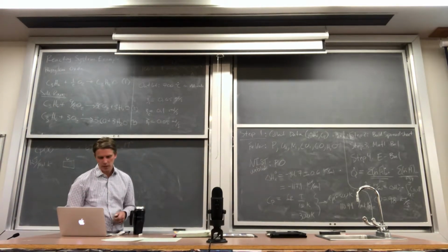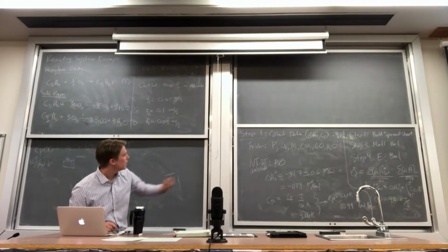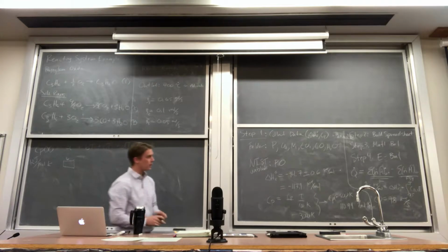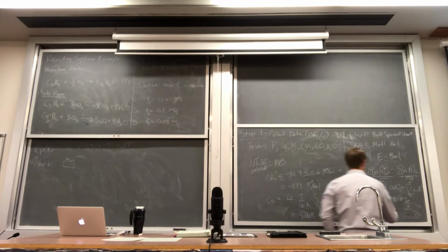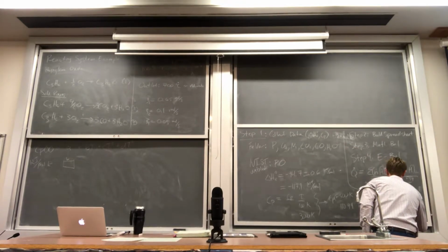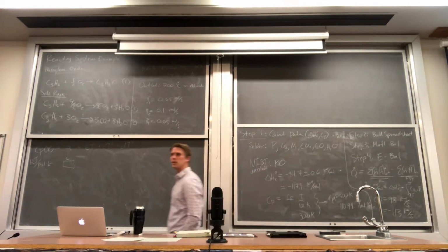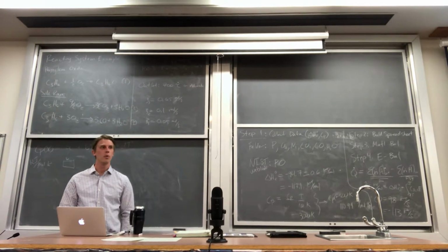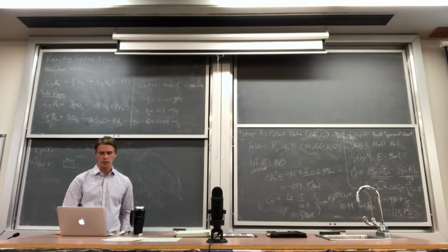Now let's say, for example, I don't trust my propylene oxide heat of formation. Let's change it to the minus 117. How did that change our result? It's significant, actually. Pretty significant. It changed it to minus 113. So that could be a big issue, potentially. I mean, that's a fairly substantial change. That's a 10% or more difference just from having a little bit of uncertainty in one of our terms.